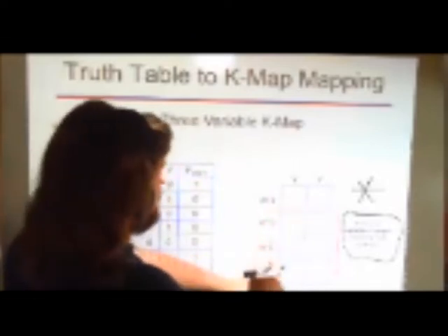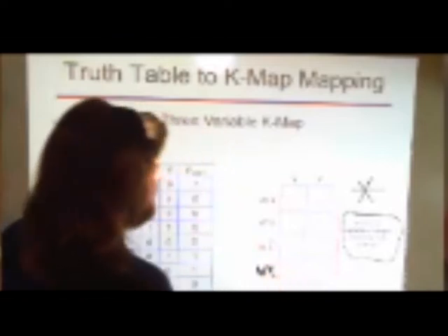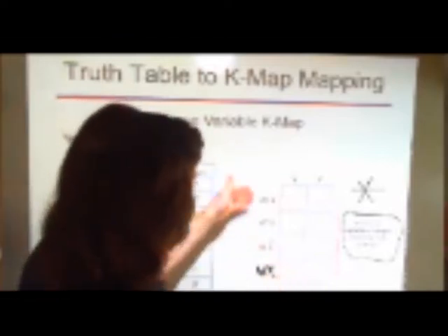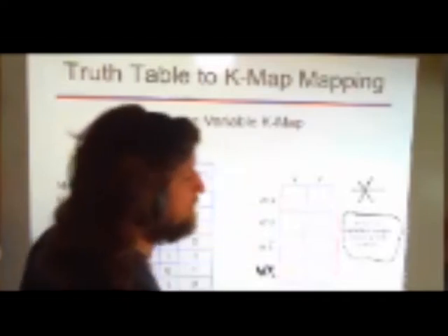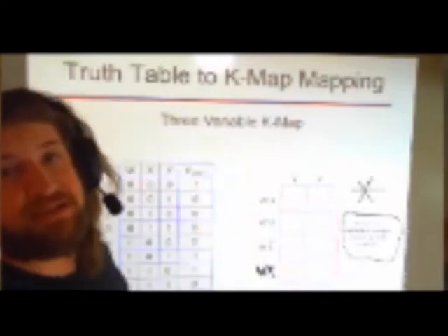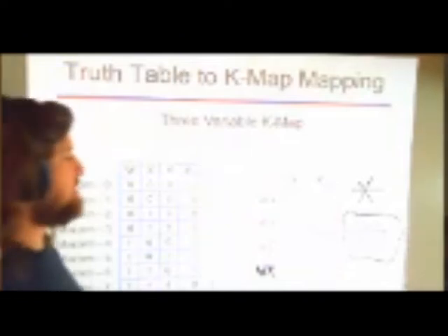They're like, oh, I just want to take care of that and then have just WX plain at the bottom because that looks cleaner to them. Here's all the zeros, here's all the ones. They have the two possible mixed combinations in there. It won't K-map correctly. You won't get the correct circuit simplification. The whole process is based around the expectation that only one variable will change every single row.